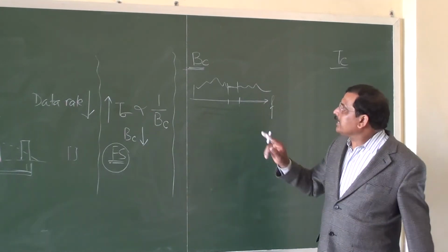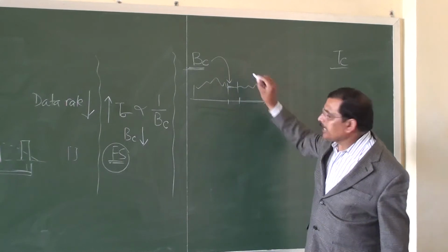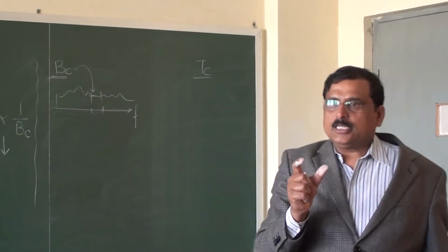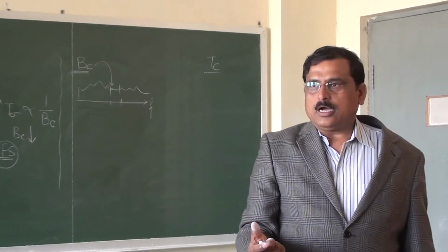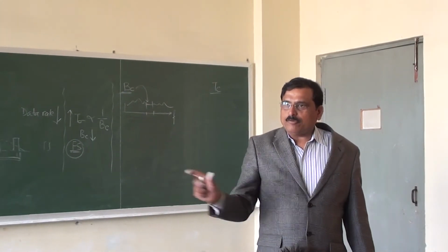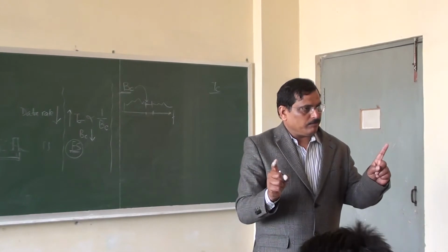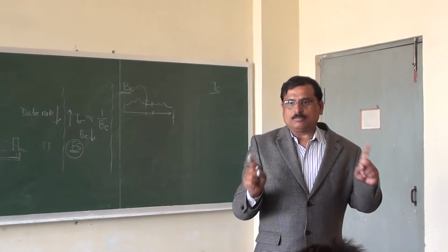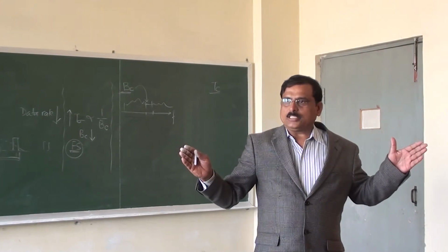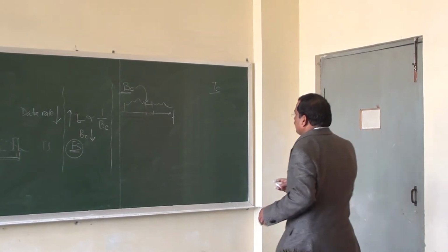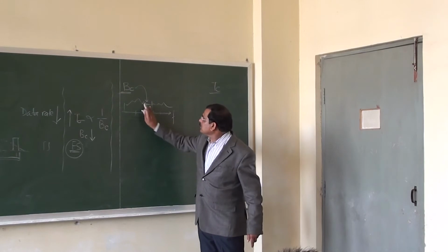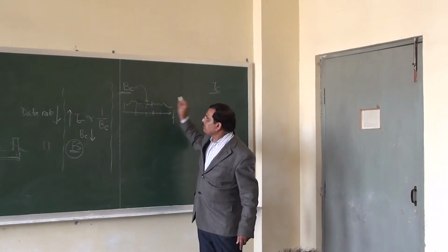So we need to understand, in order to define the coherence bandwidth, this is the span over the frequencies for which the channel is going to exhibit invariable behavior. The channel is going to show you constant gain and linear phase response. This duration of the frequency is known as the coherence bandwidth of the channel. Some channels will have a wider coherence bandwidth. That means some channels will be so static that over a span of much longer frequency, it is going to exhibit almost the same gain.